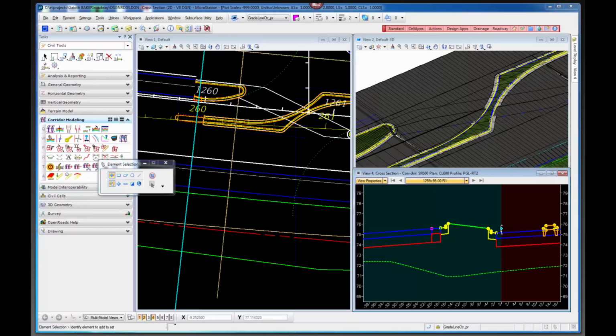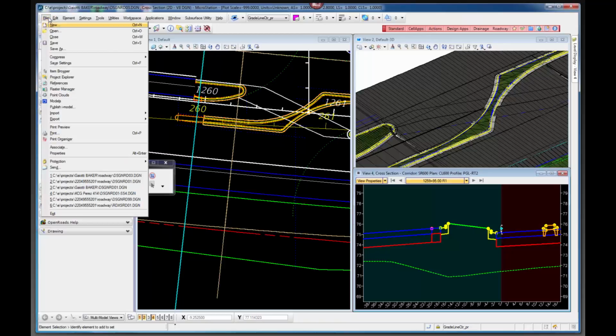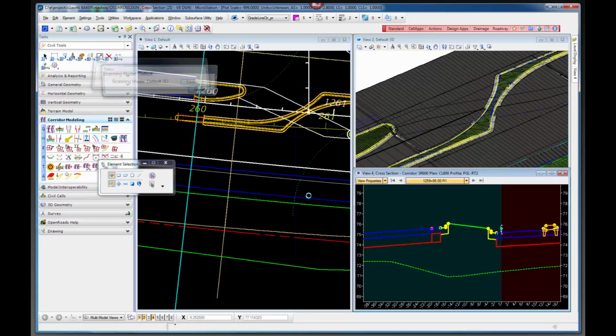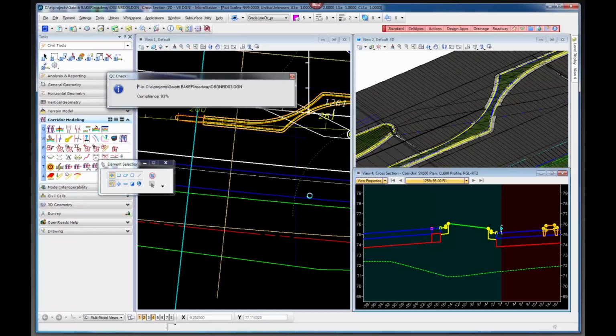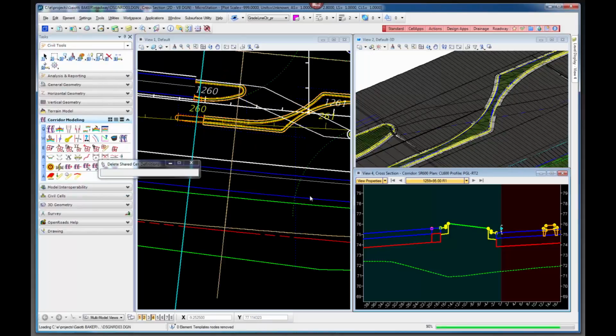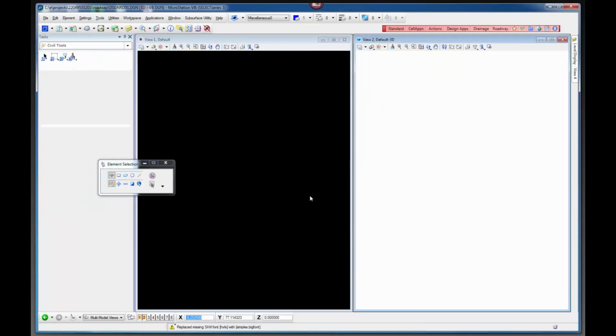Is plateauing similar? That's a good question. If you want to plateau an intersection, essentially you're going to use a parametric constraint, and that's probably easier to show in this other data set, since I actually have an intersection out there, and it processes faster. The easiest way to do that is to put in 3 parametric constraint lines.